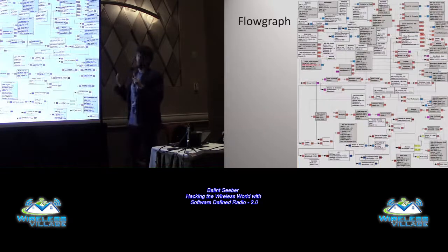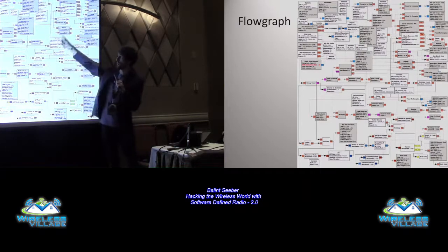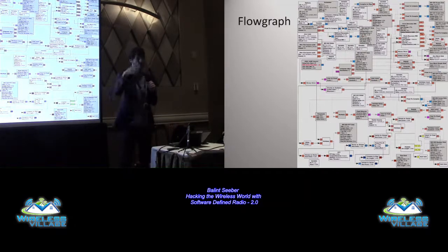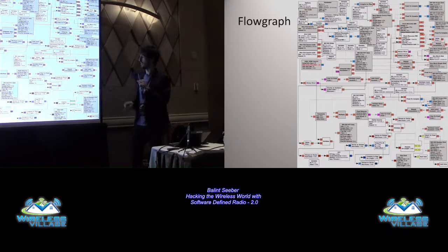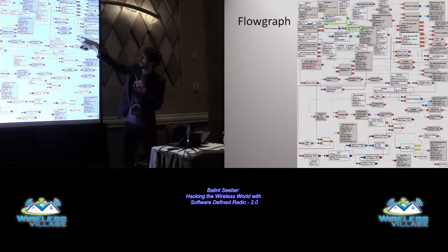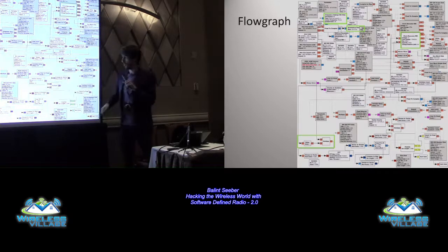So, you know, we always say, oh, flow graphs are easy, just throw a couple of blocks together and you're all sweet. I told a bit of a fib in the previous one. I hid all of the disabled blocks. So the disabled blocks are in gray, and I produced all of those plots by sort of adding these graphical sinks along the way to probe the signal. But this is more a complete picture. I get a lot of crap about my flow graphs, but anyway. So those blocks that I was telling you about there, you've got the frequency translation, Quadrature Demod, clock recovery, figuring out what the baud rate is.